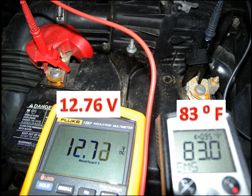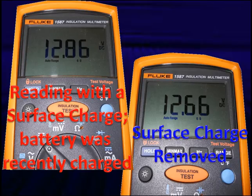Why is that little tester better? Because it pays attention to all this information right here. The reading on the left with the red writing, there is a surface charge and this battery was recently charged. On the right, the surface charge has been removed. Maybe we've hooked up some test equipment. We've been playing with our scan tool a couple of minutes. It would be perfectly normal to see 12.6. But initially, you're going to see close to 13 volts, like we see on the left. If we don't, the vehicle that just pulled in hasn't been charged.